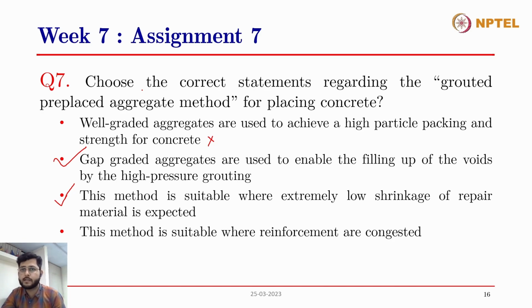The grout is essentially the cement slurry or the mortar slurry. So that grout will fill up the voids within the gap graded aggregate. Essentially, the grout should have particles of a size that will be able to fill the gaps present within the aggregates already placed in the formwork. Therefore, gap graded aggregates are first placed in that formwork, and then grout is pumped. It will become a concrete after it gets pumped and fills the voids within the gap graded aggregates. So the second option is therefore true.